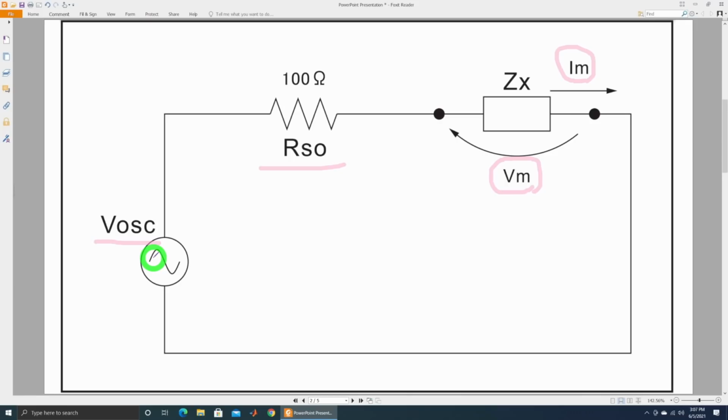No device really is only purely resistive or capacitive or inductive. There are always a mixture of all of them, and they have to do with the parasitic of the devices. I'll talk about that a little bit at the end. So why not just build an LCR meter like this? And what's the deal with having these 4 connectors to the front of the instrument? Well, if you have a very inexpensive LCR meter, like a handheld one, or a really cheap one, that's basically what they're doing. They're doing something really simple.